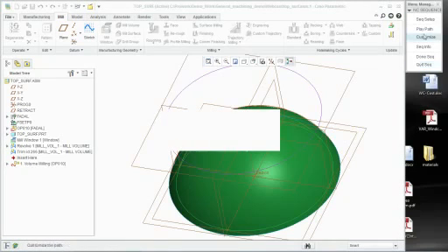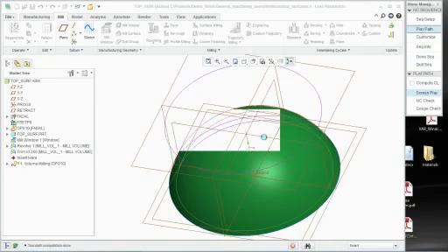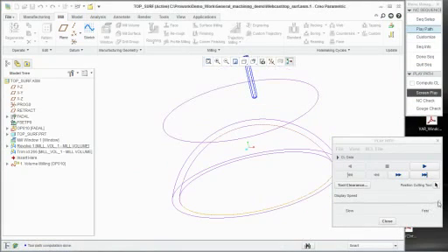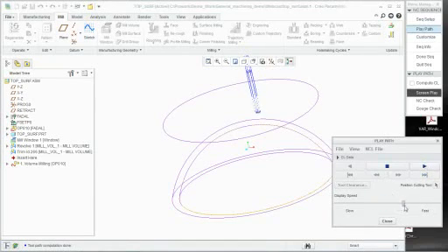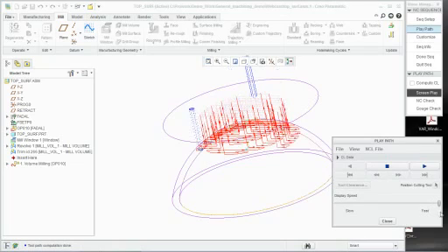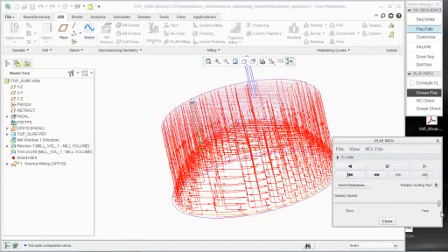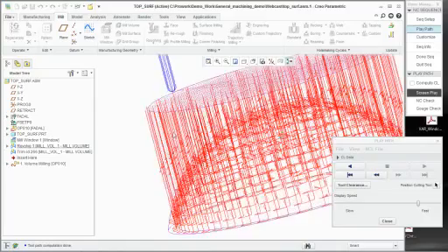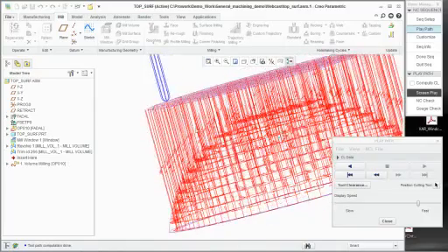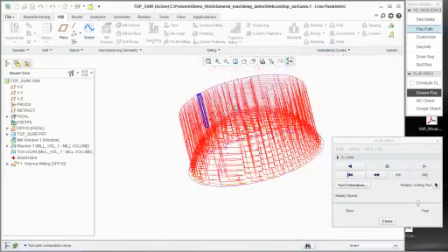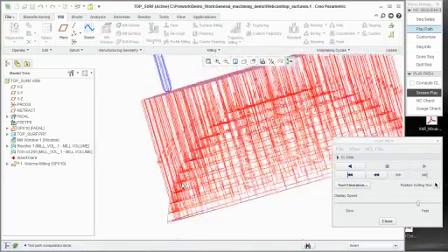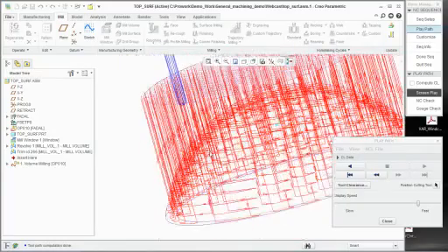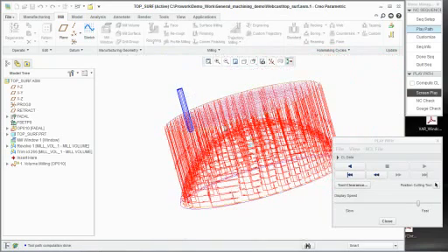And there we are. I will play this path. And now what you see here, slow this down, is that notice how it pays attention and conforms the shape to the top, and you have some pickups that you have right there, but it actually conformed the shape, and you don't have all of that milling that started off all the way at the top. If I changed the way that it was machining, you wouldn't get all these retracts. But it has actually conformed the shape to the mill volume that we're using, instead of just doing a whole bunch of air cutting out here. I know this is a bunch of air cutting, but don't pay attention to all the retracts that you see.